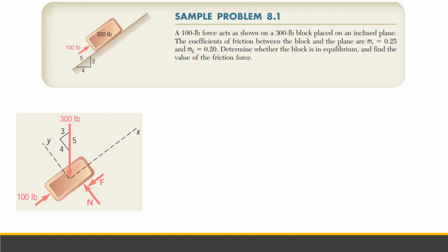Usually in an inclined plane, we use the coordinates in this position. So x is parallel to the plane, the plane is our x-axis, and the normal or perpendicular to the plane is y. So what we will resolve into components is only the weight. The other forces are not, because we are shifting our axes along the surface or along the inclination. So this is the slope.